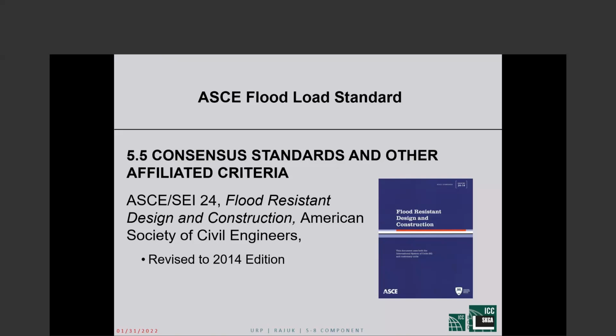This was developed with FEMA money, and this standard talks about hydrostatic loads, hydrodynamic loads, debris impact, which is a major thing when there is storm surge, and also scour of the foundation, which is another huge problem.